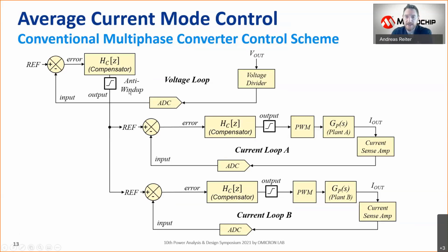For simplifying that system, or to address more phases than maybe just two, maybe you have a higher number of phases, that would not really scale well. At some point you might be required to reduce your control frequency and control every other cycle, for example, and then your bandwidth drops, and the capability of meeting the design specs is at stake when you're failing to provide enough performance to run the complete control system in real time. So that is one limitation.